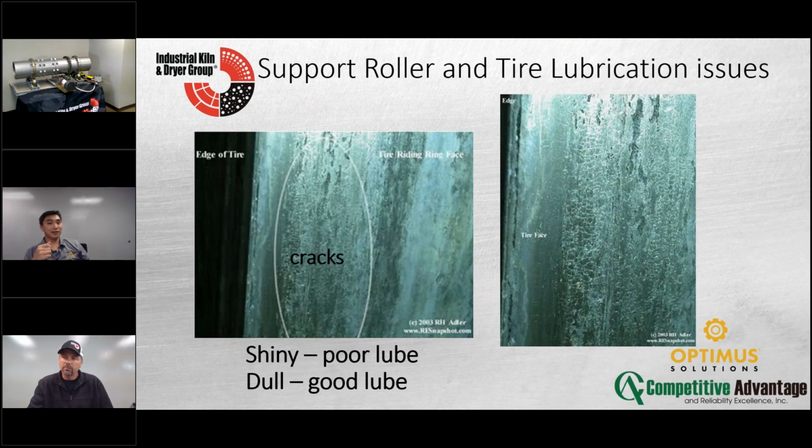And some of this is lubrication related. Most of these units, you want to keep it at graphite blocks or graphite lubrication. When you have grease or oil, even though it might look shiny and nice, you will see pitting occur. I think one of the questions is how much pitting is bad. You'll actually see this peppering of pitting all the way across. I would consider that bad, especially if you went from graphite to this and the pitting goes up.